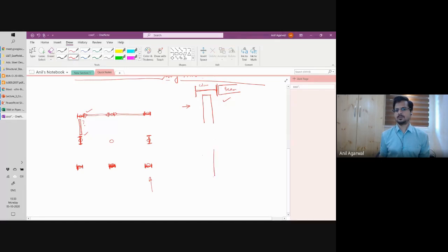So this is the web of the column. Okay. Now the beam has come here. If I weld this beam to the web of the column, the web is very thin usually. So once I apply any kind of a moment demand here, the web is simply going to bend and it will not offer much of a resistance. And strengthening the web is much harder, because the kind of elements that you had available before, those are not available with the web. So the web is very weak in this axis, and you cannot provide a rigid connection with the web.